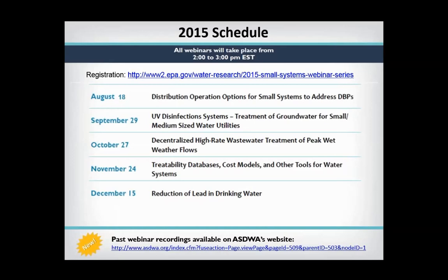Now, most places the compliance monitoring points are not out in the distribution system, but I think from a public health standpoint, it's certainly wise to look at what the treatment changes would do. In some cases, there may be further immobilization of some of the contaminants, but I do know of a couple, one system for sure, where they added a mixed phosphate chemical hoping to reduce the lead.